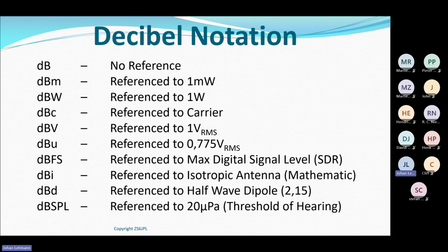When we look at dBs, you'll see these funny things appearing behind the dB symbol. When we talk about dBs without anything behind it, there is no reference point, no baseline. I'm purely comparing two values. It doesn't matter if it was a start or an end value or a midway and endway value. I'm comparing two values without a reference. That gives me straightforward just dBs.